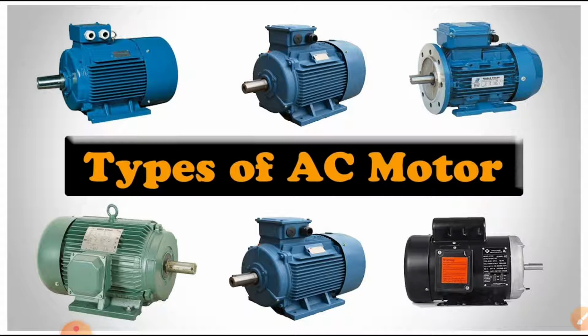Mainly, the basic difference is the speed control. The speed of DC motors is controlled by varying the armature winding or field winding. We have already done this in our laboratories. But in our AC motors, the speed can easily be controlled by varying the frequency. In the case of DC, there is no frequency. So these are other advantages of AC machines. Hence, we mostly prefer AC motors wherever we require cheap and best motors.